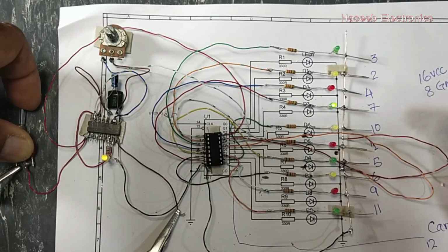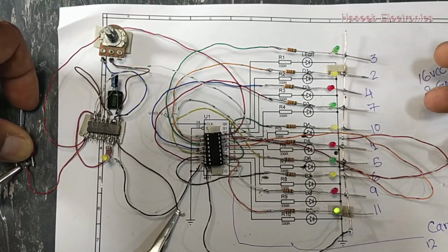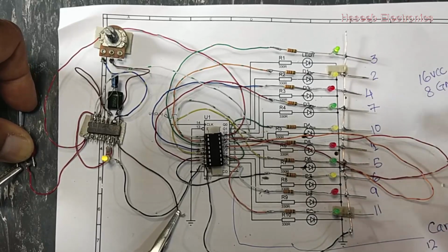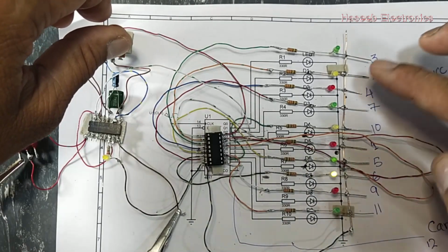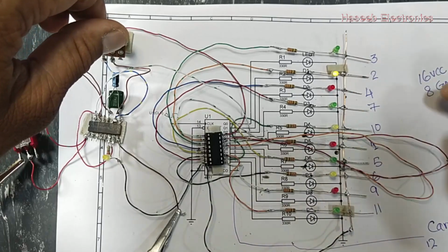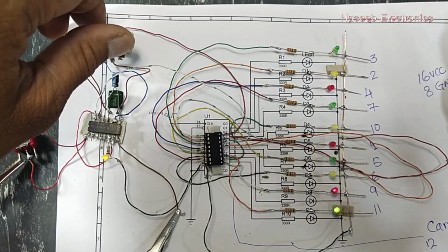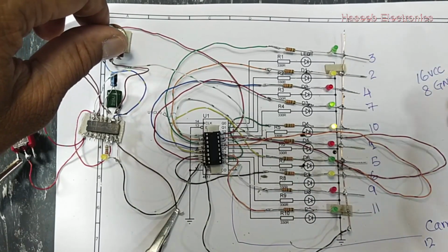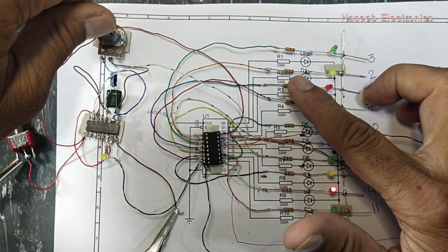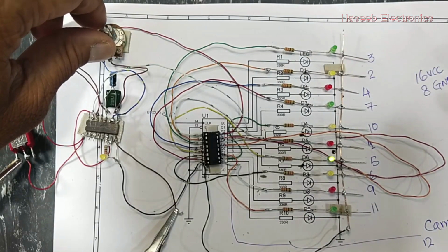If you want to start the sequence from 0, then we have to make a reset circuit which will disable its operation, and after a specific time, make a delay time circuit, a delay start or soft start circuit. You can make a soft start circuit using an RC time constant. If you can make it in circular style, you can make it easily. And if you want to integrate a big number of LEDs, you can use a switch, a MOSFET, and you can use this signal to drive that MOSFET, and that will work.